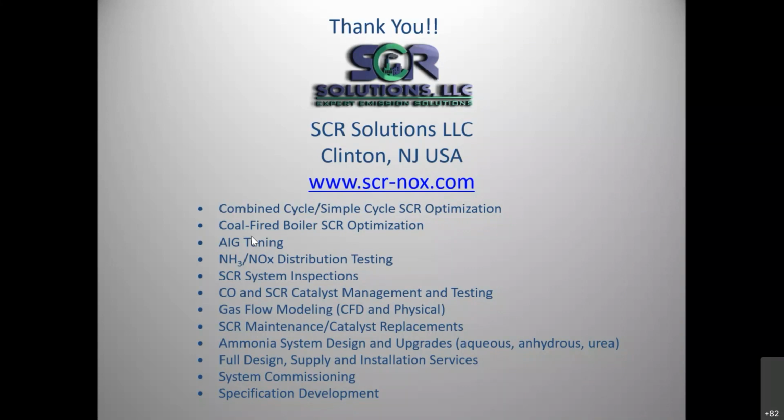So we told them we can't fix that, but we did make the new AIG out of stainless steel. So we got rid of whatever sort of rust or scale would come out of the AIG itself, which isn't a lot, but it's something. And then they also had us add cleaning ports in the AIG, which was actually in one of the slides I could show you, where they wanted cleaning ports in each lance to address this problem. So we just put in a threaded pipe cap and a nipple so they can go in there during an outage if they needed to, and bang on the pipe and vacuum out each section of lances.